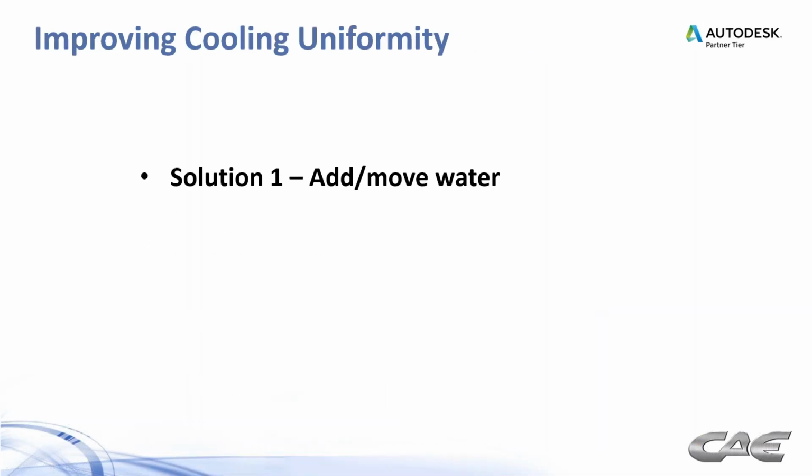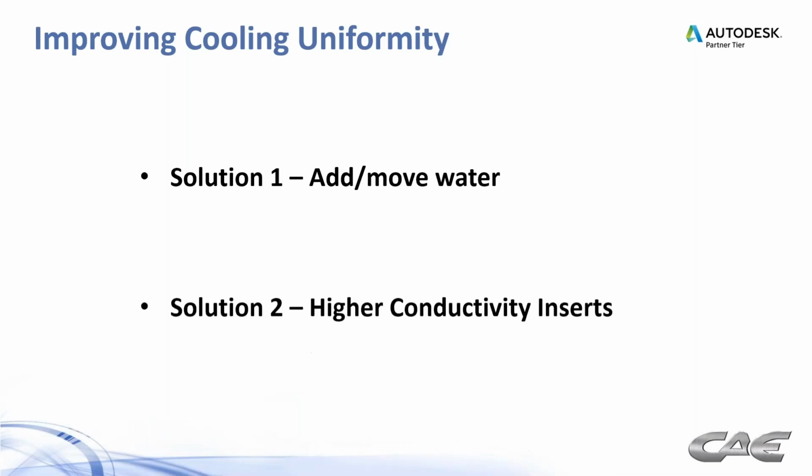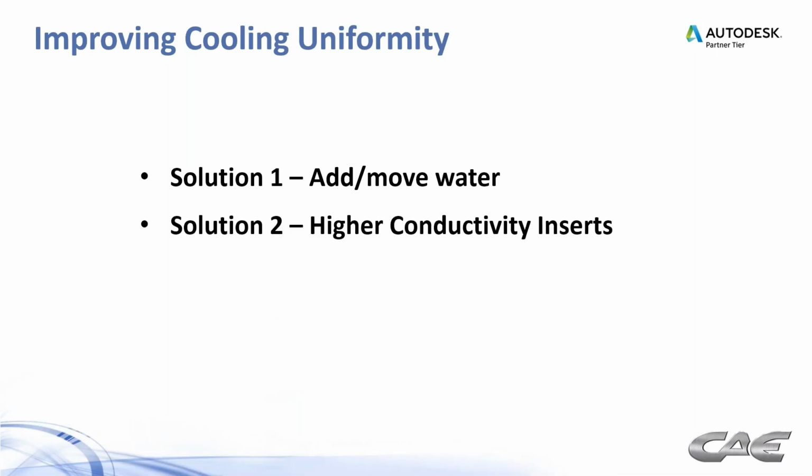So how do we improve cooling uniformity? Solution 1, add or move water. Solution 2 is to add higher conductivity inserts. Solution 3, maybe we go to conformal cooling. Conformal cooling is all the buzz these days, right?